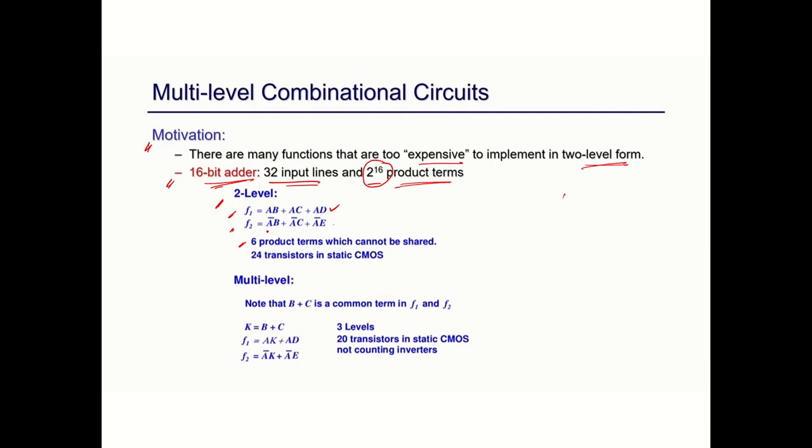And if we just check, as it is 6 product terms, it means 6 AND gates are there. So if we just translate it, each AND gate, if you just realize, at minimum 4 transistors are required to implement this one. So minimum 24 CMOS transistors are required to implement this particular function. Are you getting this one? Yes or no? Yes, sir.